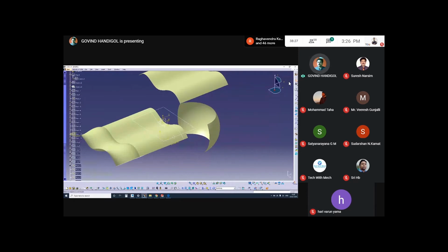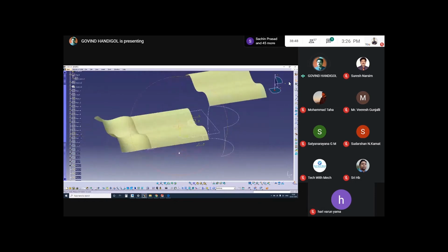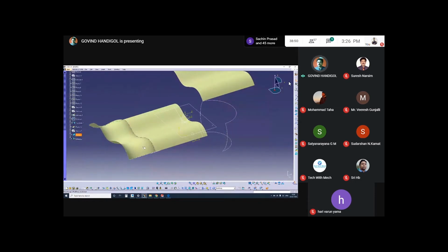extract the curves from this wireframe geometry. Here there is a command called extract. Sorry, I would like to extract the edges. No propagation, point continuity means all the edges are going to be extracted. Hide it. The curves are there. Curves are extracted from this. These are a single entity. Extraction is a single entity. I have to disassemble to make independent entities.